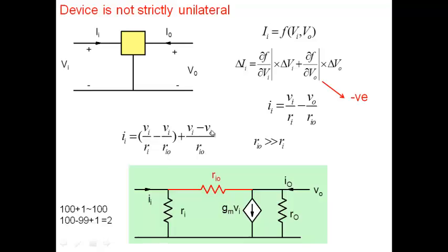But remember, the small signal model is an approximate model already. We are already making approximations, we are calculating results which are accurate within maybe 10% error or so. Now, whether you keep Ri0 or whether you don't, if it results in less than 1% error, why are you doing it when at other places you're committing errors as large as 5% or 10%? There's no point in keeping a term which is not introducing that much error.